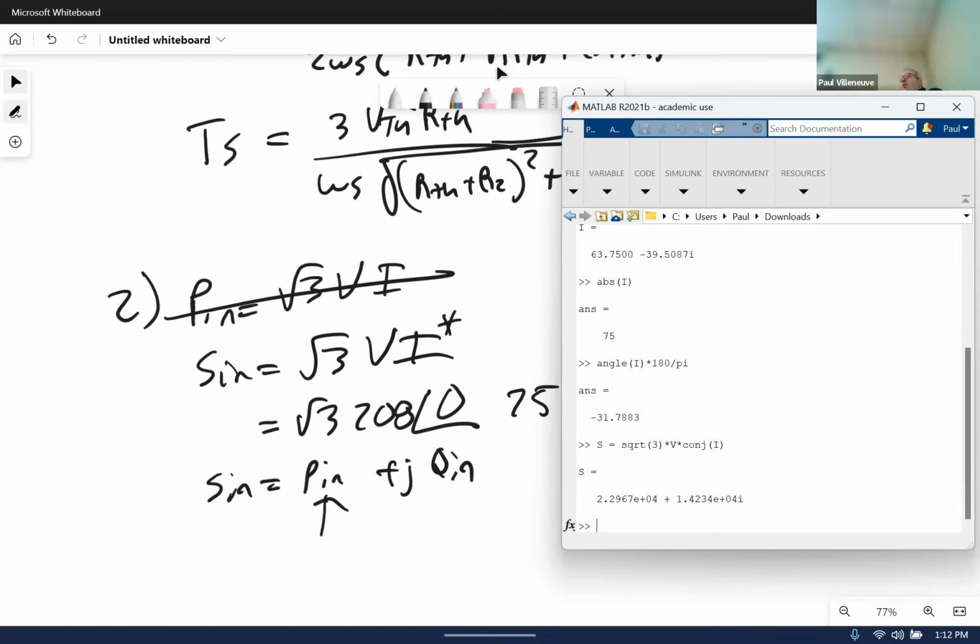So even if we do go to a renewable energy grid, which has solar and fuel cells, those put out DC. A lot of the other technologies will put out an AC, but they usually will convert to DC because it's what's called a freewheeling AC, which means it's not 60 hertz, and you can't connect a non-60 hertz to a 60 hertz system. The concept is we need to be able to continue to use AC because motors are just so practical when they're AC.